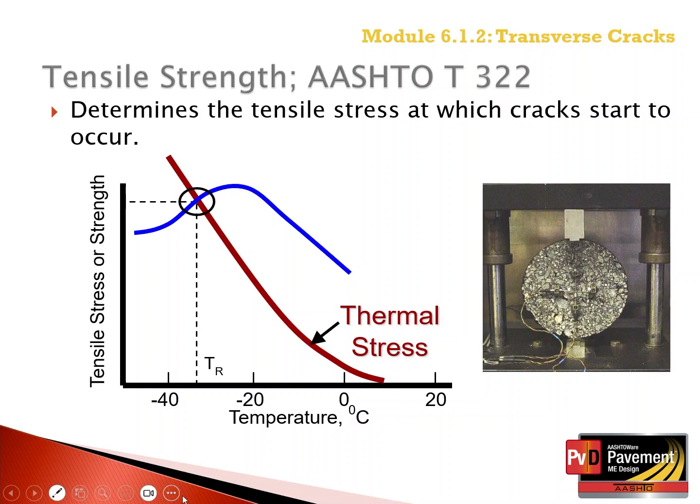At very cold temperatures, as noted previously, the indirect tensile strength will decrease, as shown on this slide, because microcracks start to develop at the interface between the aggregate surface and binder. The reduction in tensile strength is not simulated in the Pavement ME software, as we previously mentioned.